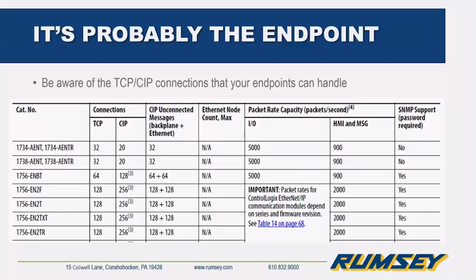So if, for example, a piece of Ethernet cable is receiving EMI, electromagnetic interference, and turning some zeros to ones or vice versa, the TCP error correction mechanism goes into play and retransmits. This occupies even more network bandwidth and can easily cause communication disruptions. All Ethernet cable is not created equal. The correct selection of Ethernet media is unimaginably important in an automation environment, but that's a whole other topic that I won't get into now.